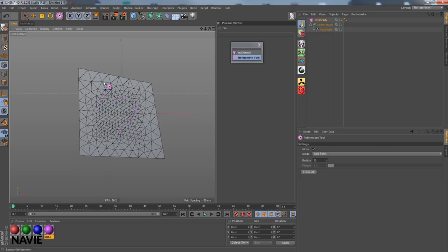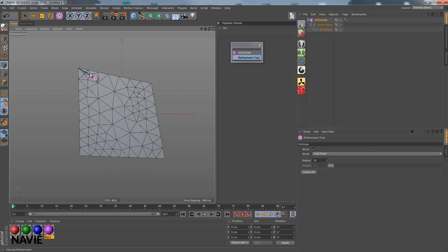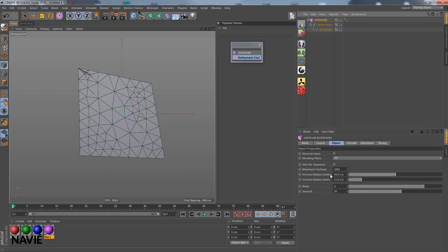At this point, I would like to mention a constraint of the triangulation. Let's move these 2 points with a low refinement rate up here, near the boundary. This will not work actually and give us kind of a false result here, because imagine that at the boundary we have, as we can see here, a big radius. So polygons are quite big there, but we want them to be small there. So this kind of collides, and you have to make sure that this constraint is not broken.